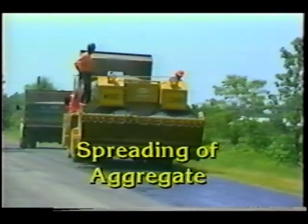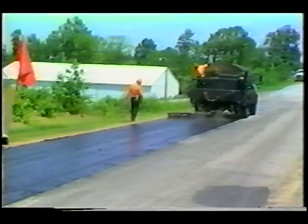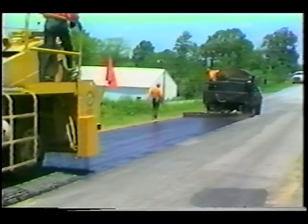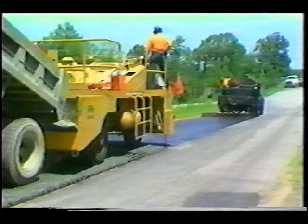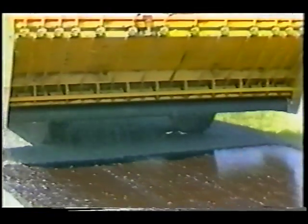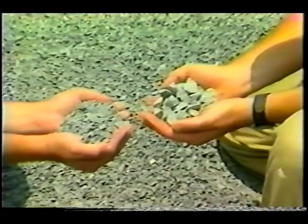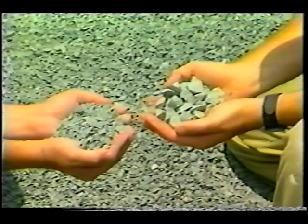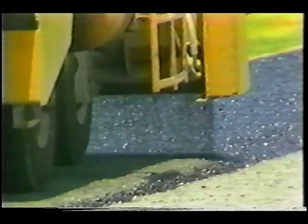The fifth step in the asphalt chip seal procedure is the spreading of aggregate. Spread the aggregate immediately after the distributor sprays the asphalt. The aggregate should be placed before the emulsion breaks. Emulsion is chocolate brown when put down, but turns black when the emulsion breaks. The water is released into the air, leaving only the asphalt. The size and type of aggregate used depends on several factors, including the number of layers being installed and the type of emulsion being used.